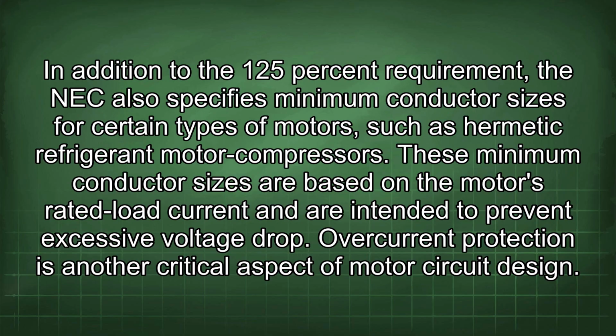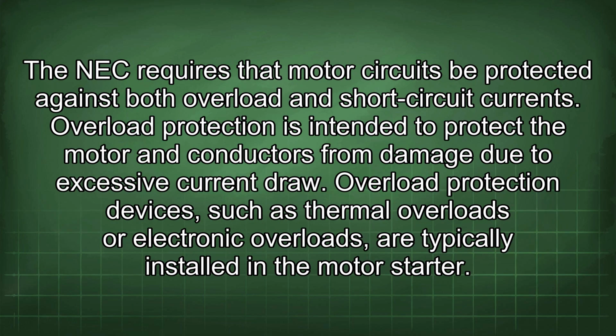Overcurrent protection is another critical aspect of motor circuit design. The NEC requires that motor circuits be protected against both overload and short-circuit currents. Overload protection is intended to protect the motor and conductors from damage due to excessive current draw. Overload protection devices, such as thermal overloads or electronic overloads, are typically installed in the motor starter.